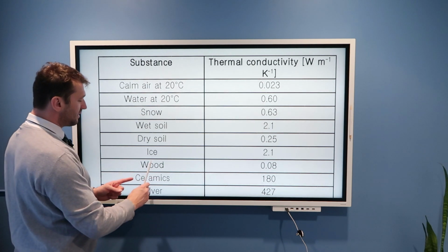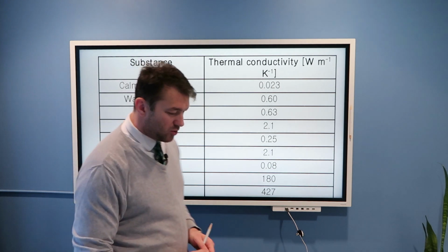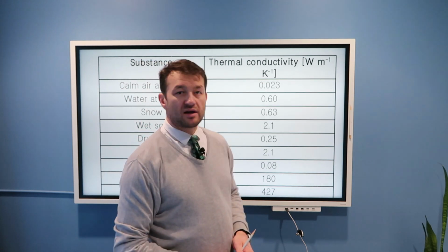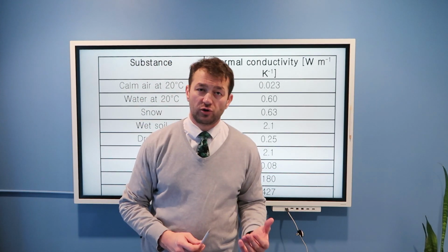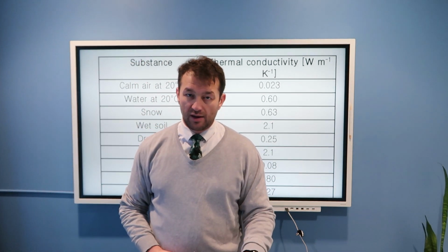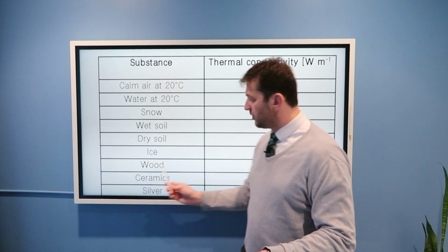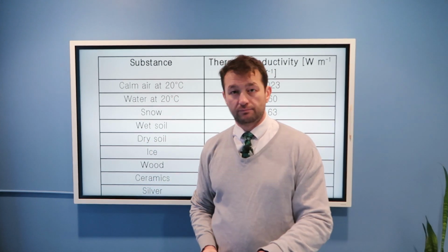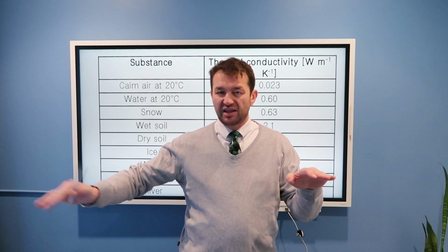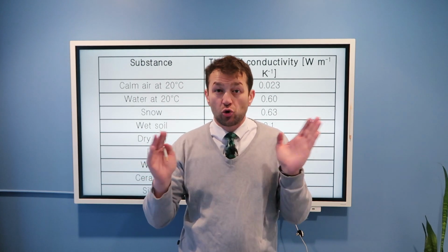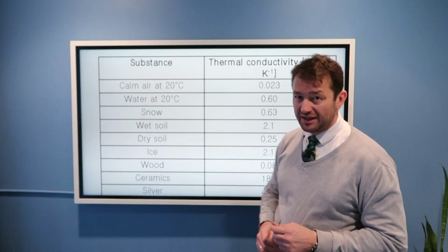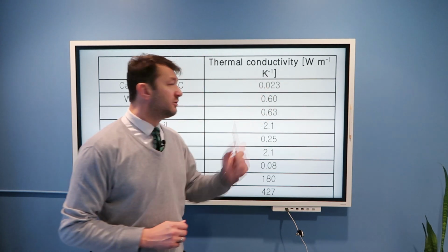I purposely put here wood and ceramic, because you know, if you have a wooden floor and you wake up in the middle of the night and you start walking, you don't feel cold when you are walking on the wooden floor, but if you have some ceramic, you feel very cold. And your mother would often tell you, don't walk on ceramic barefoot, it's colder. She is wrong. Both wooden floor and ceramic floor or some metal floor are at the same temperature, room temperature, whatever it is. But ceramic or various metals, they have very high thermal conductivity.